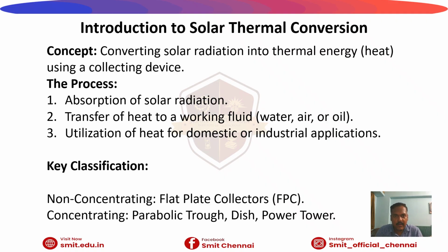Okay, introduction to solar thermal conversion concept. Converting solar radiation to thermal energy, to heat energy, using a collector device. The process is absorption of solar radiation first. Second is transfer of heat to the working fluid, water, air, or oil, and utilization of heat for domestic or industrial applications. There are two classifications. One is non-concentrating, another is concentrating. In the non-concentrating type, we are using FPC, flat plate collectors. In the concentrating type, we are using parabolic trough, dish and power tower.